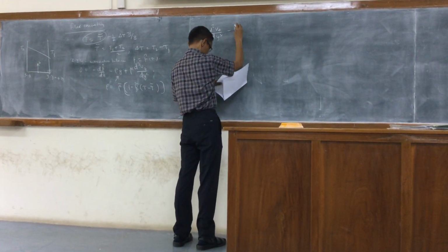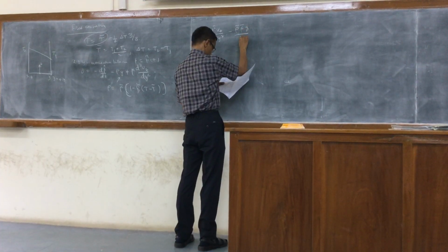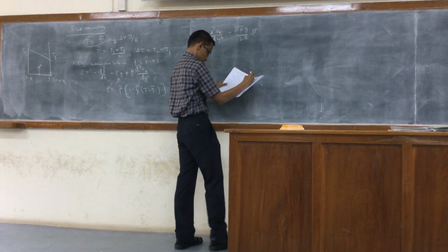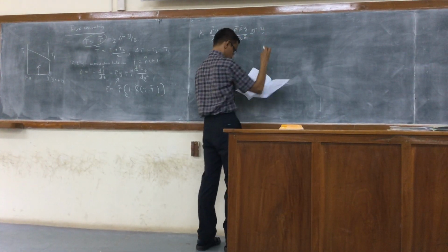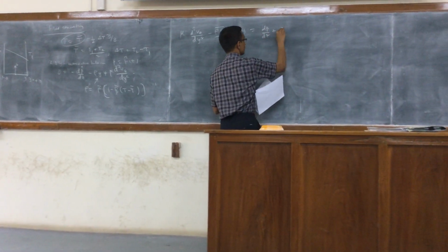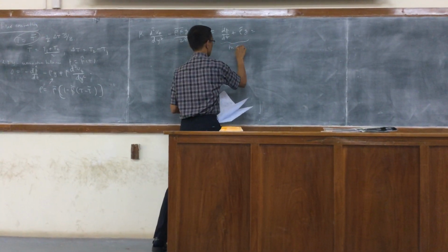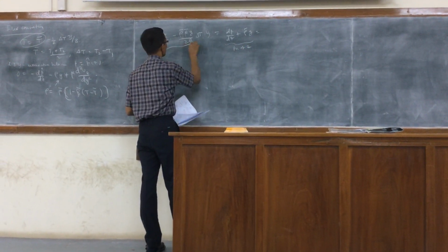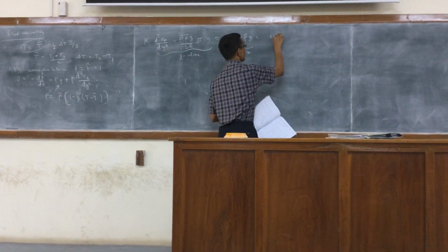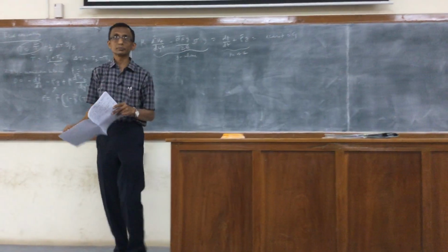Minus rho bar beta bar g by 2 delta T times y over b is equal to dP by dz plus mu d squared v_z by dy squared. This is a function of z alone, and this is a function of y alone. So the two can be equated to a constant given by C1.